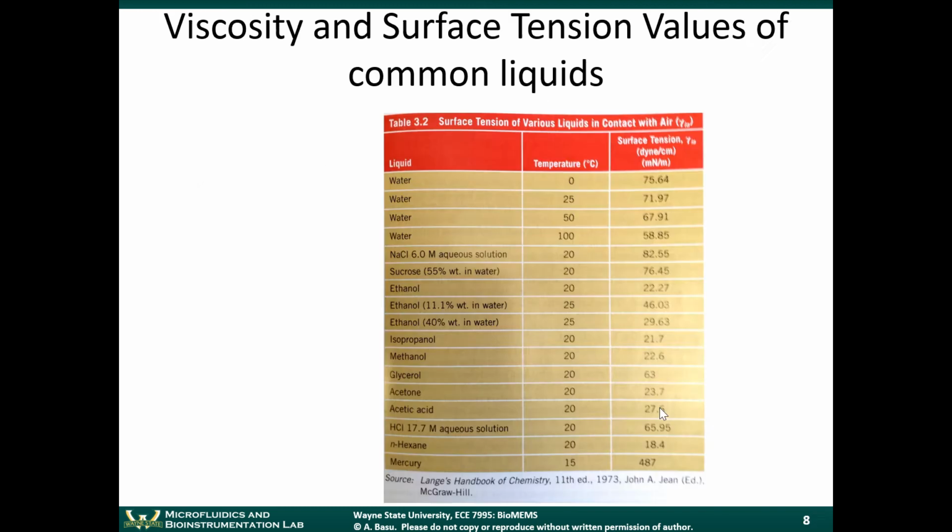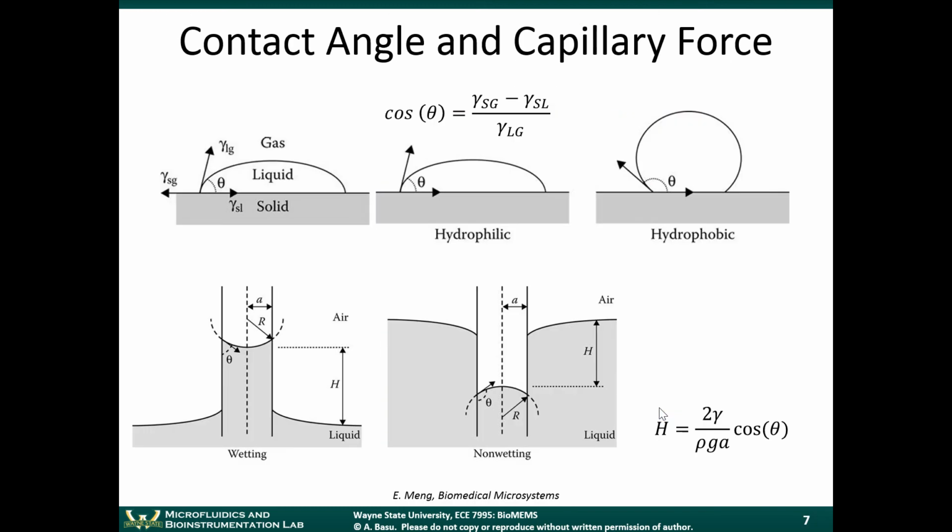That's hydrophilic, yes. Right? So this is if you have a hydrophilic channel, right? The hydrophobic would actually not fill? Yeah, hydrophobic will do exactly the opposite. So this can be a problem too. I'm glad you brought that up, Jeremy, because if you have a hydrophobic channel, the channel will actually resist you putting liquids into the channel. Okay, and in which case you just need a pressure pump to drive fluid into the channel.